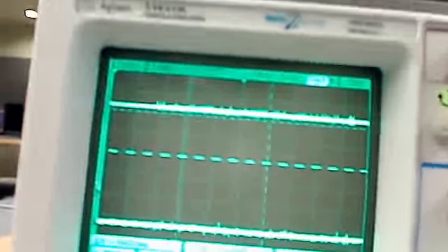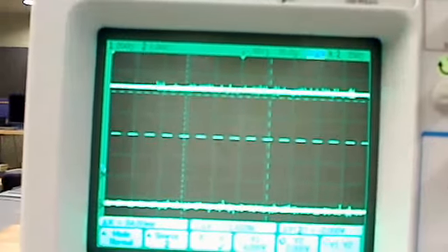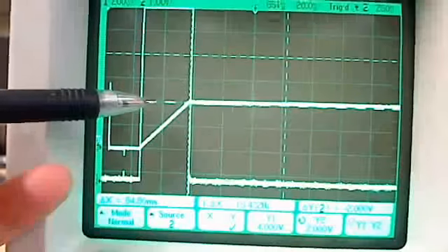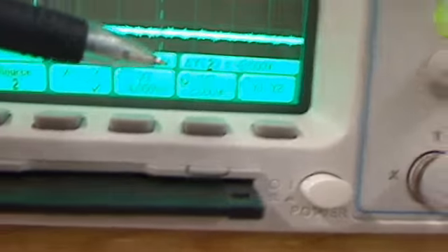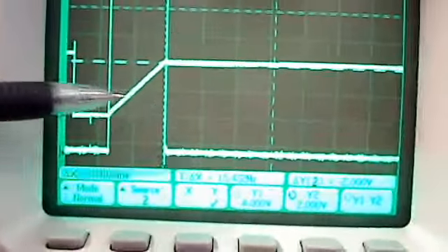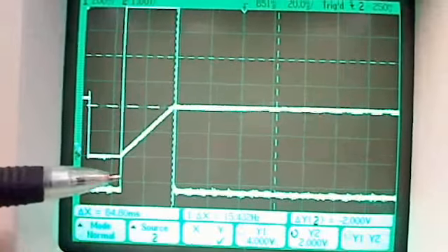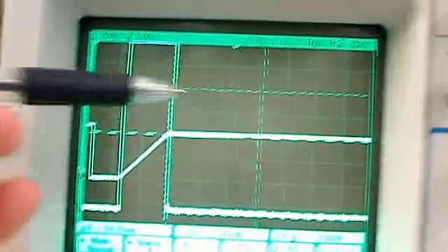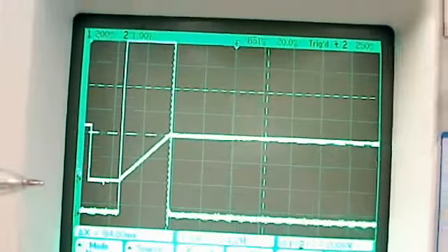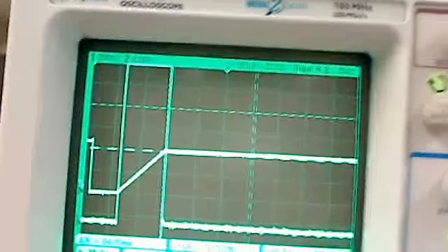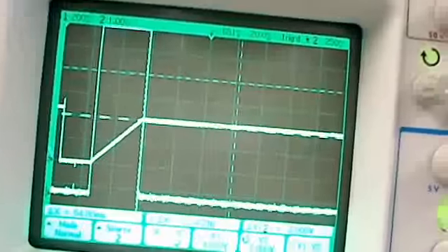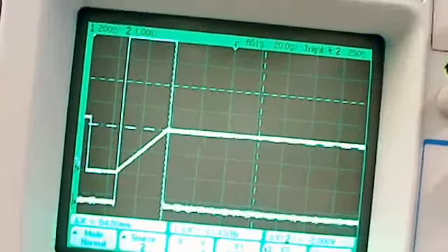You see it reloading. If you look, you see the thing has stopped working, and hopefully it will restart. There, it restarted, and now we see that it's going to this different cursor level, which I've set for 2 volts, and it's taking about half the time to integrate that it was before. So we have effectively a 64 to 2 volt D to A converter that we've built, and by changing the numerical value that we pause for in the program, we can change the D to A converted value.